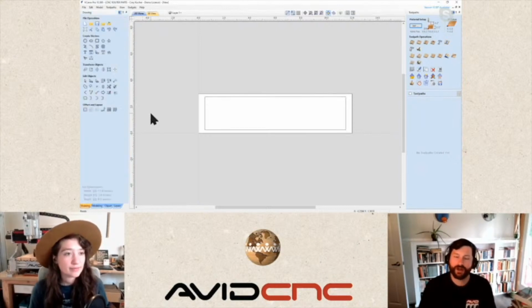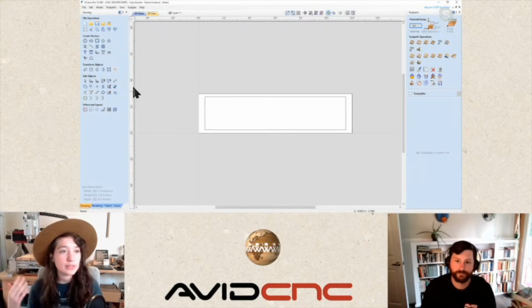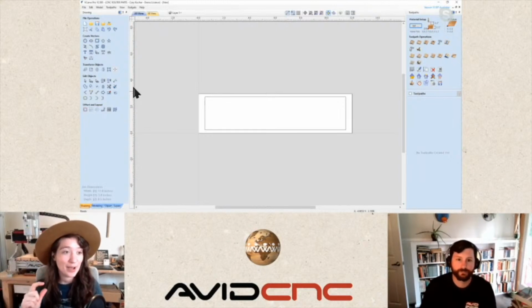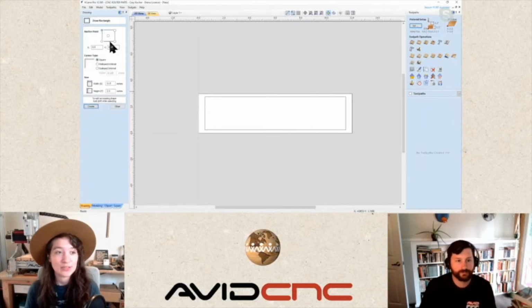Perfect. And so with a typical profile toolpath, you would see 100% tool engagement with a very shallow depth of cut, right, Sami? Right. But I think in this case, we're going to try to focus on doing side milling rather than having a very shallow depth of cut, because in this circumstance, we can try to preserve the tool life by making sure we're using the whole tool and not just the bottom edge of it. Cory has a really great technique in which we can approach this.